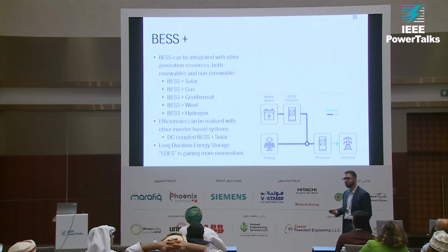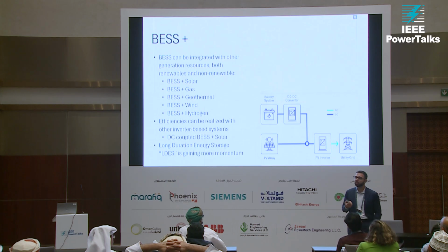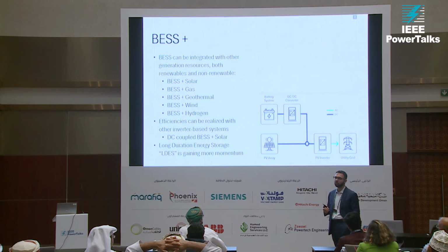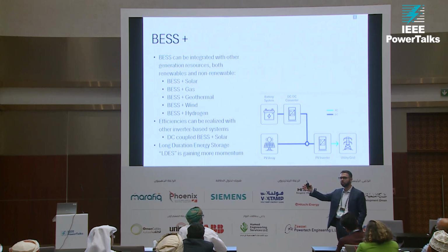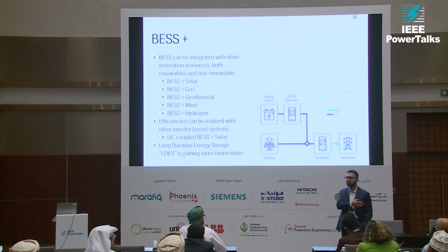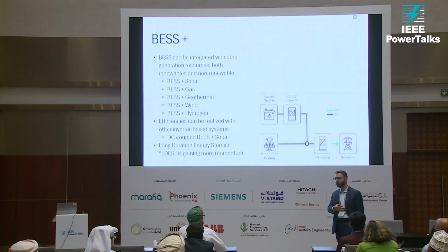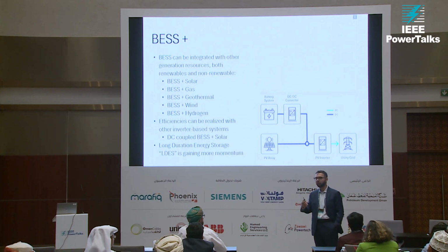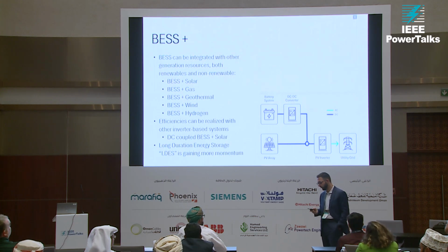With solar, for example, we like it for capturing clipped energy. Clipped energy is a very common issue in solar where, for example, if you need 100 megawatt solar delivered, you build 130 megawatt DC solar. You have solar overbuild. For most of your day, that solar overbuild is being clipped, pretty much going to no use. So instead of clipping the energy, you charge your batteries if you have a DC integrated system. You use that clipped energy to free charge your batteries for later use. So that's maybe one of the reasons we use that in solar.